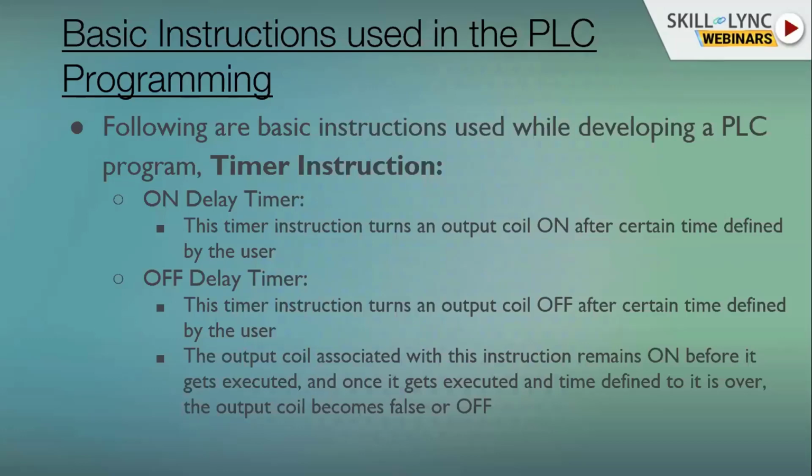We have different types of timer instructions here. An on delay timer makes a delay of some seconds, which we need to define, and after that delay it will switch on the output.